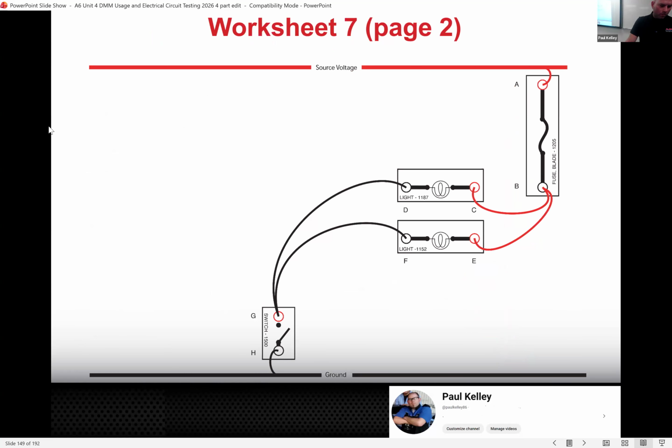All right, so if we were to look at this, let's do some predictions. Can anyone predict, right? I won't even trace this. We're just going to pull some numbers. Can anyone predict what the voltage available at point E should be where I just pointed? 12-ish? Yeah, let's just go with a source. Something like that, but 11.9 and 12.0, it's effectively the same number. And if it's a car that's got a charged battery, maybe it's 12.6, and if it's a car that's running, maybe it's 13.8 or whatever, but source voltage there.